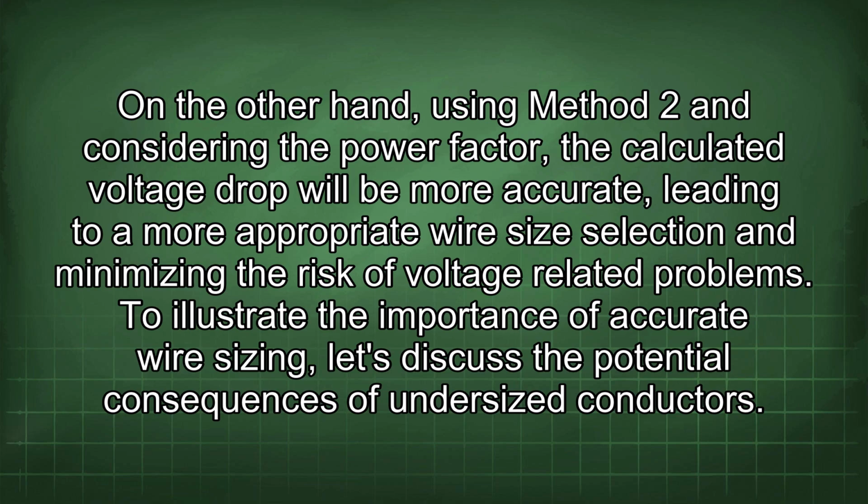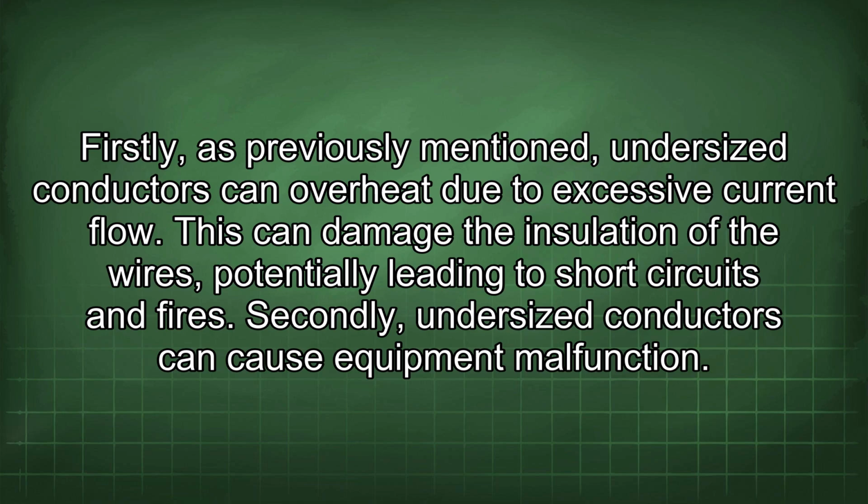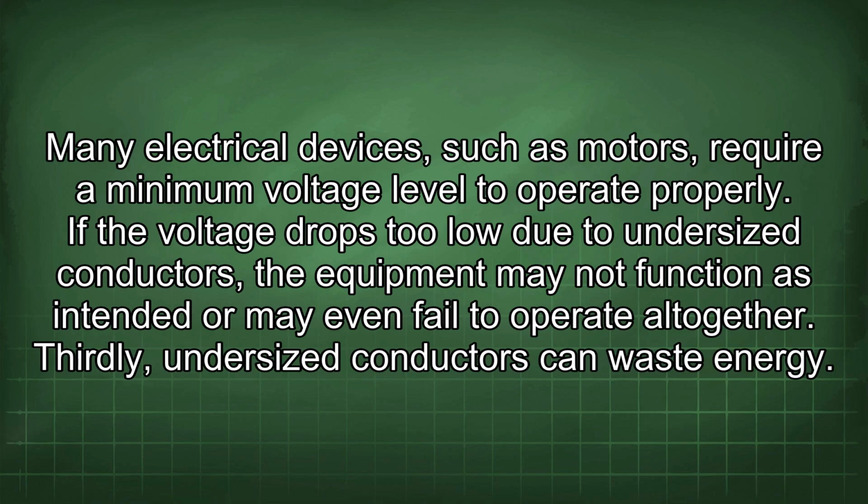To illustrate the importance of accurate wire sizing, let's discuss the potential consequences of undersized conductors. Firstly, as previously mentioned, undersized conductors can overheat due to excessive current flow. This can damage the insulation of the wires, potentially leading to short circuits and fires. Secondly, undersized conductors can cause equipment malfunction. Many electrical devices, such as motors, require a minimum voltage level to operate properly.